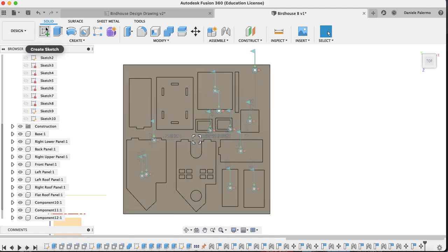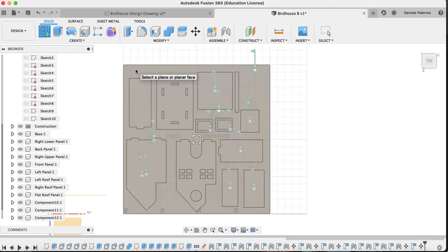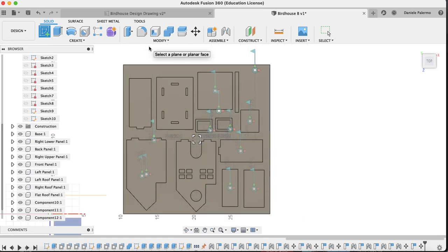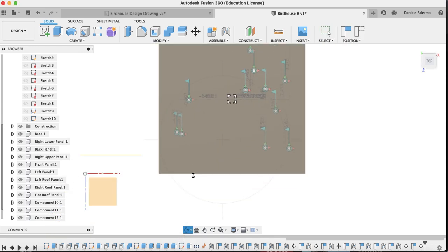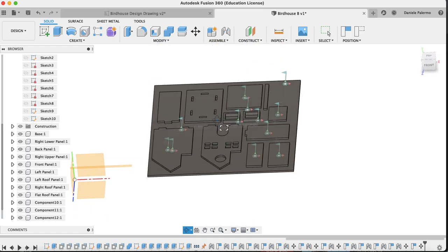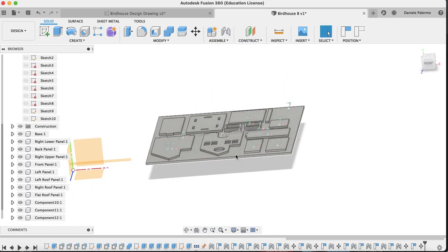Okay, so here we go. Let's create a sketch right here on top of this surface. Okay, actually, let's not create a sketch there. Let's create a sketch in between. Let's create a midplane. So we are going to create a sketch in between this top surface here and this surface right there on the very top of these bodies. All right, so we're going to create a midplane that is in between those. So here we go, watch. We're going to go to construct, midplane.